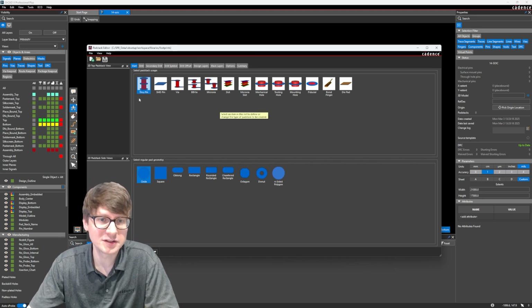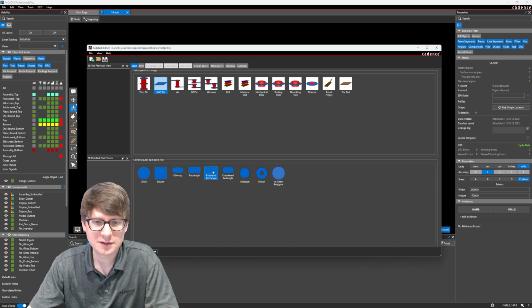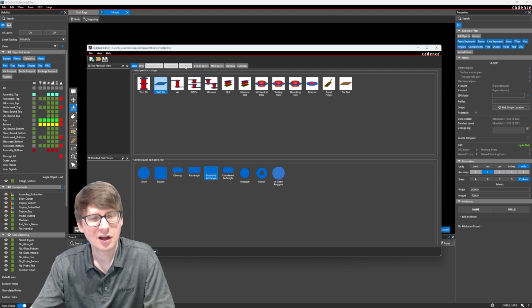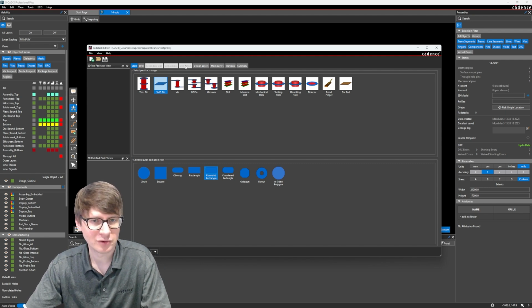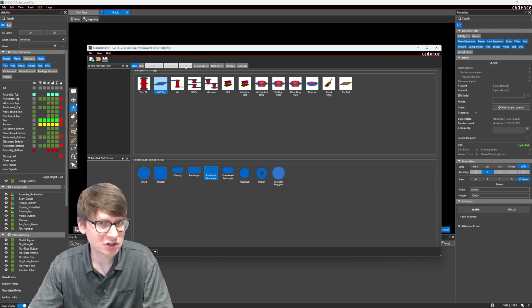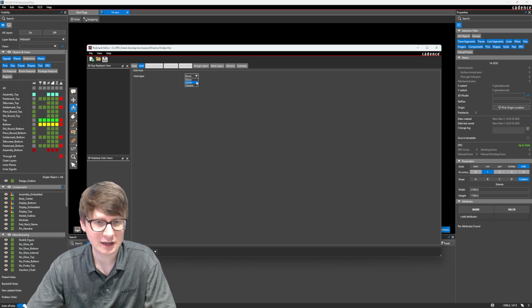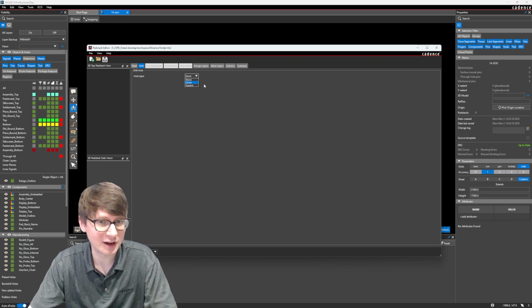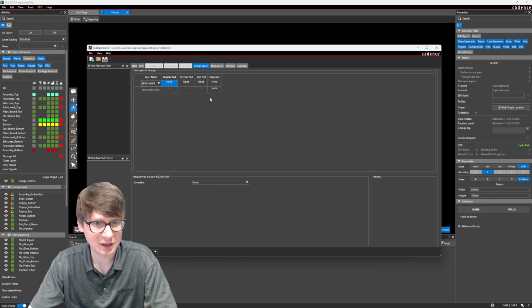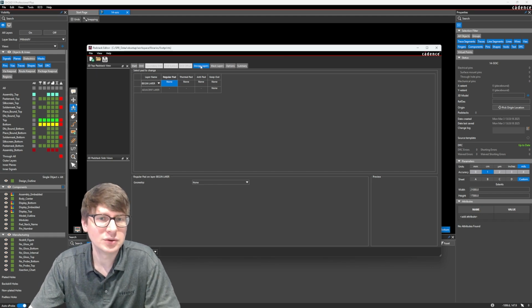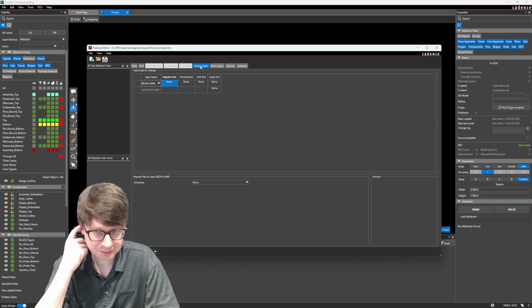Now, what we're creating in this case is an SMD pin, and it is this rounded rectangle shape. And since it's an SMD pin, you'll notice that things like the secondary drill, drill symbol, drill offset, all of those tabs just got grayed out, right? We're not going to have any additional drills on this pad. If you, for some reason, need a drill on your SMD pad, we do have that option, but again, probably not. And then what you want to do is go into the design layers.